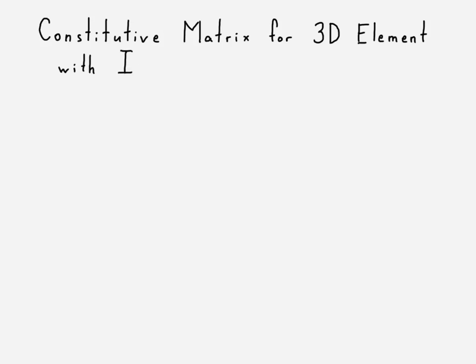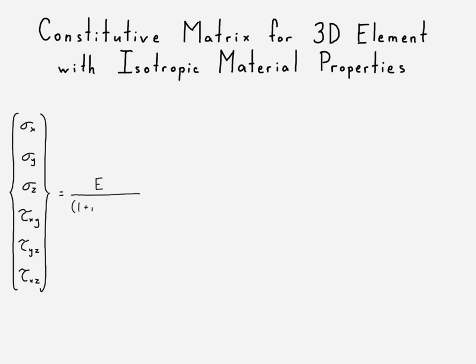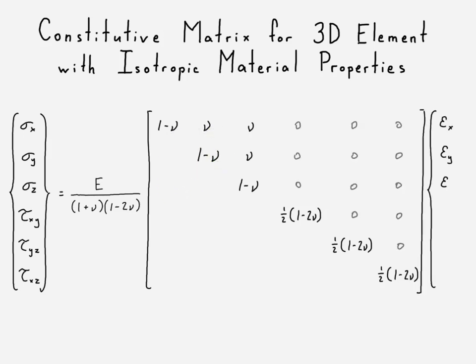We're going to combine all that into our constitutive matrix equation, which is now a 6x6 equation. We're going to show the isotropic version of this. Composites or anisotropic would be much more involved, so we'll keep it simple for now. All we're doing here is applying that 3x3 coupled relationship we saw for our normal stresses and normal strains, and then the direct relationship we have here, making a substitution for our shear modulus with similar terms with the elastic modulus and Poisson's ratio.